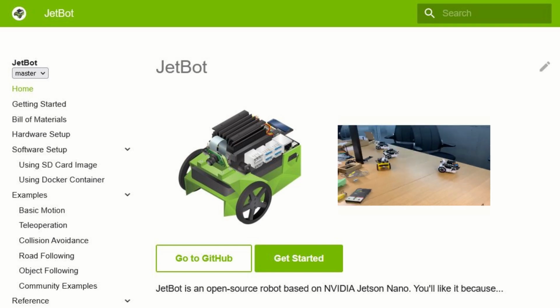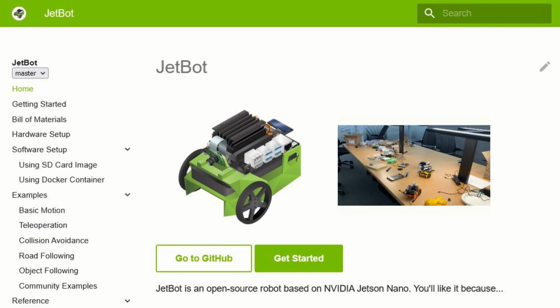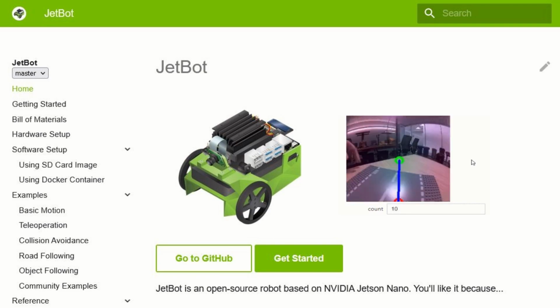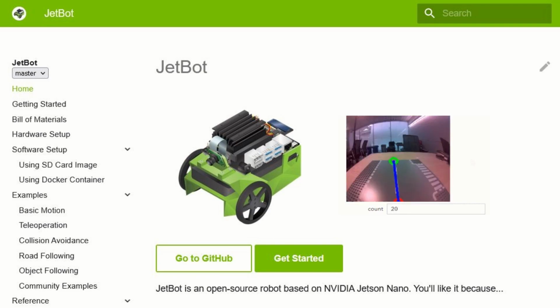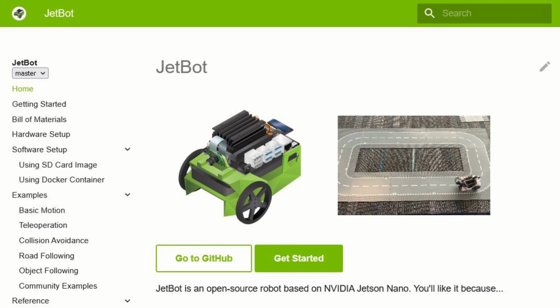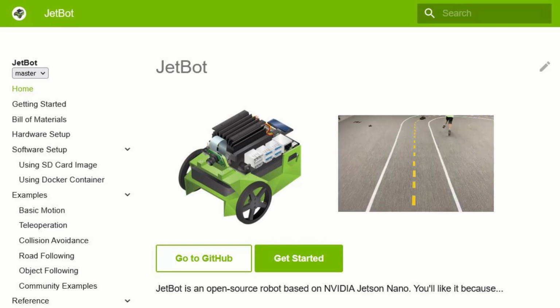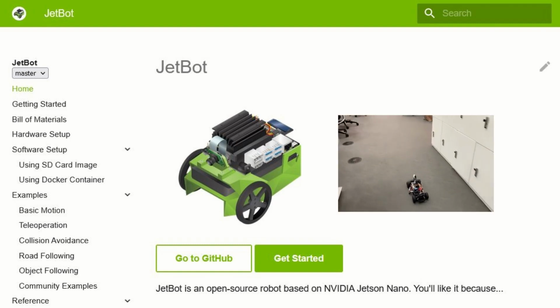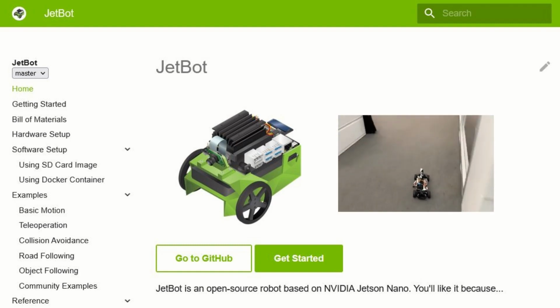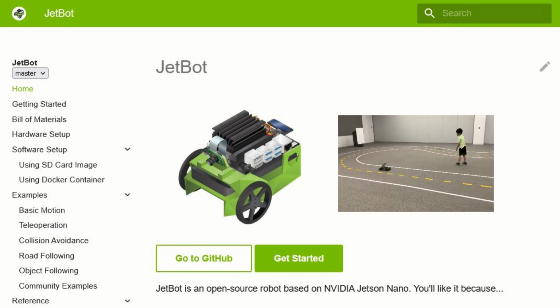Here's NVIDIA's website, and the overlaid video demonstrates the JetBot and the JetRacer. Both use a simple model that produces the steering value as output. You record several pictures with a camera and mark the steering direction on each of them. Through training, the model learns to apply the correct steering value to keep the vehicle within the street markings.